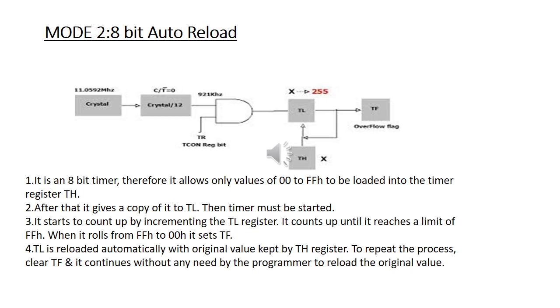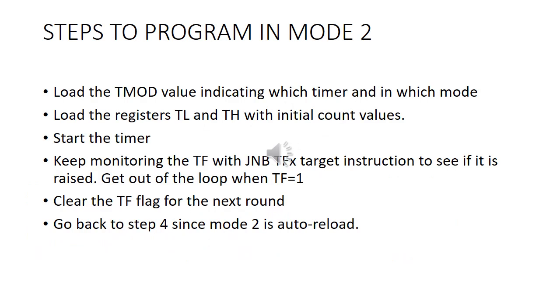So you did not load the value again into the TL register, so that will be done automatically. So it is called an 8-bit auto reload mode. Steps to program in mode 2.